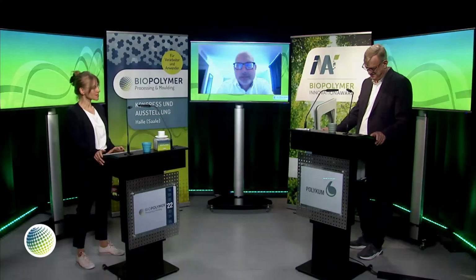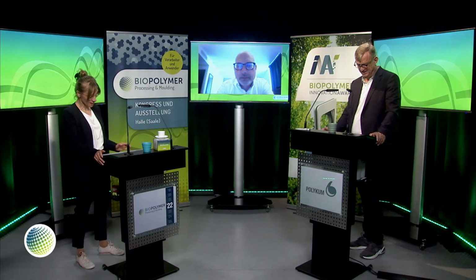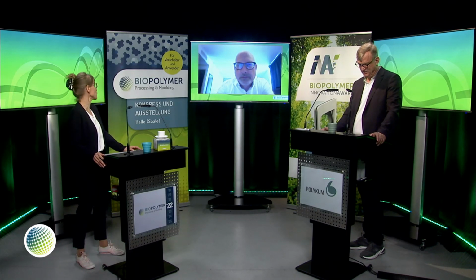We still have some time, and we have lots of questions coming in, which is good. So the next question is, how fast does your super glue cure? For all the experiments we have done, we have put the material on top of the surfaces, then we have clamped it together with a paper clip for 1 day, and then we have performed the measurements and determined the adhesion strength.